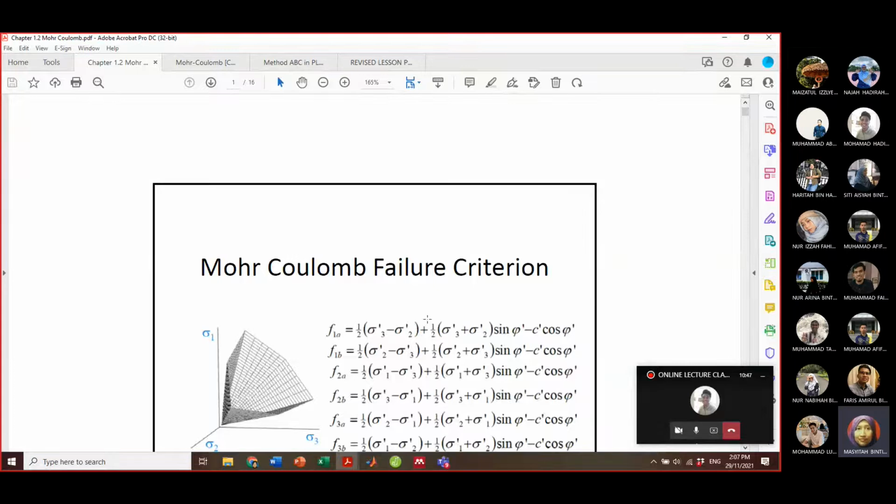But the difference about non-linear and linear, it goes and it comes back when you are dealing with design and analysis. When you are taking the real problems on site, for example, the real behavior of the soil, considering it as non-linear, you may have a good design. However, if you consider the material as linear elastic, you may have an over design. So what is the effect of over design? It comes back to the cost of the project.